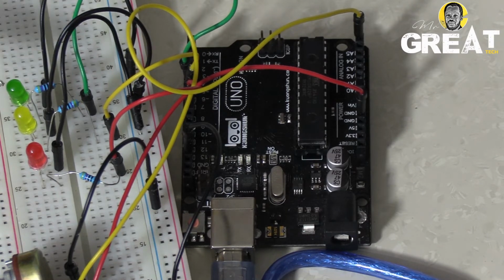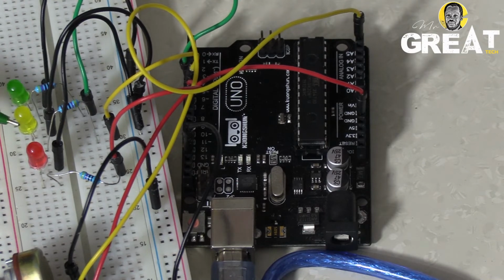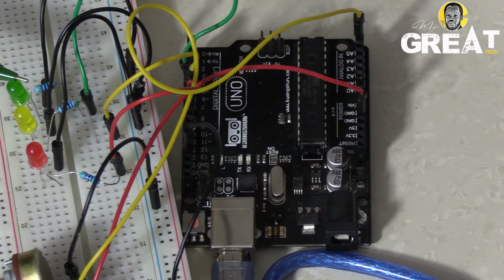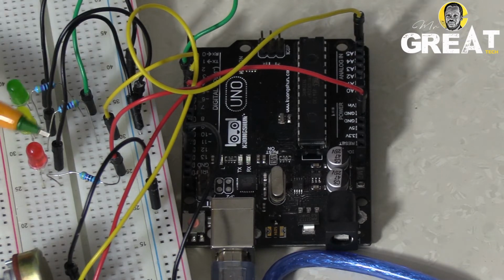Let's use a 12 volt battery as an example. So at this level, the battery is maybe 11.5 to 12 volts. It's not all that full. At this place, you have 13.5, getting to 14 volts, filled up. Then at this place, you have 10 volts and below, where your battery needs to be charged.